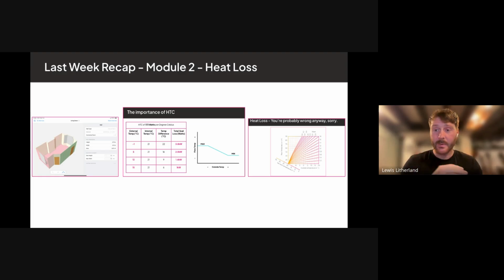And that's why we don't advise people to set the curve at whatever you thought it was going to be based on that heat loss. Set it lower and keep going lower until you realize that you're not hitting that temperature anymore. And then suddenly, okay, that's heat loss now. So again, I think this slide was just trying to emphasize: do the calculations, use the apps, get as close as you can, but then in real life, let's start thinking about things as well. And again, that's what the whole course is about.